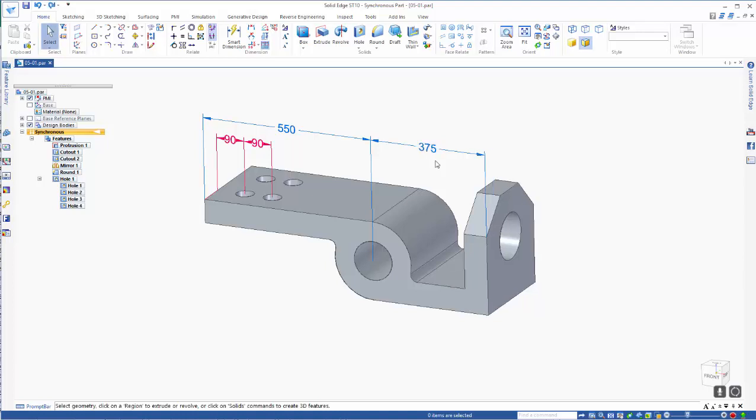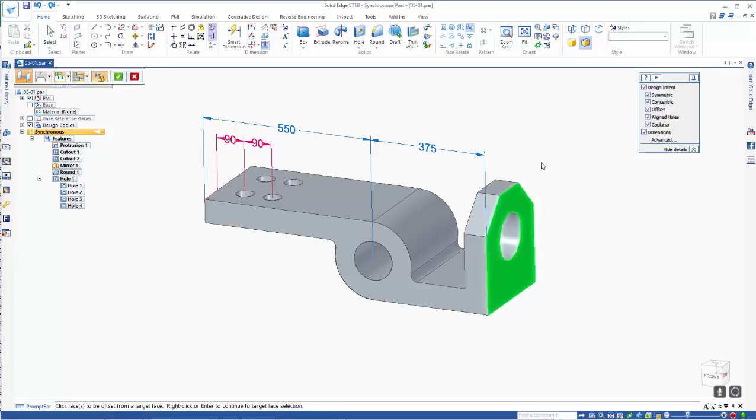In a 2D profile sketch, what you might do is have a dimension across here. We can do a similar sort of thing by defining a 3D face relate. So this defines how the model is going to behave. It's recognized that there's a 75 mm spacing between the two faces, and we can change that or just accept it.